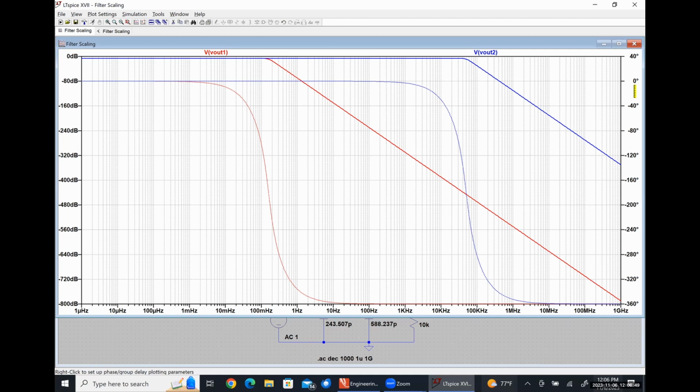Right? So that's the whole purpose of this, to make our resonant frequency go from 1 radian per second, which is what the red curve represents, to 100 pi kiloradians per second over here. Right? Now we also did magnitude scaling, but that's just scaling the impedances. It's not scaling the output of the filter at all. It's just scaling the impedances for what's available.